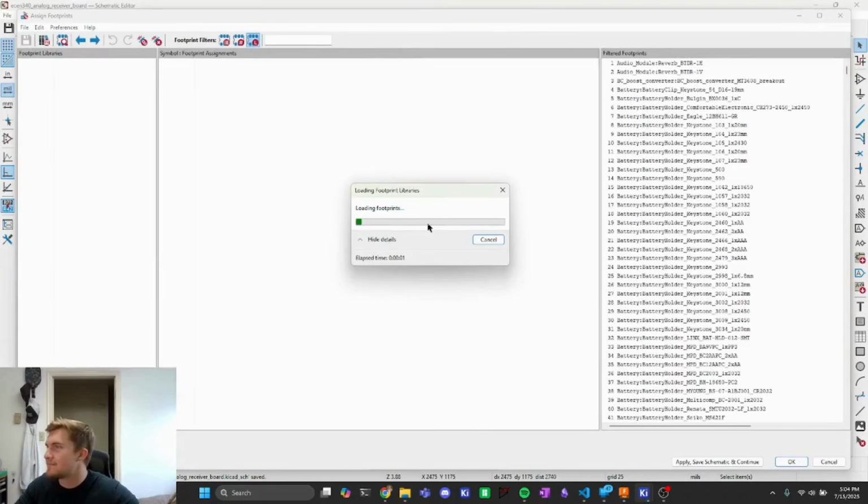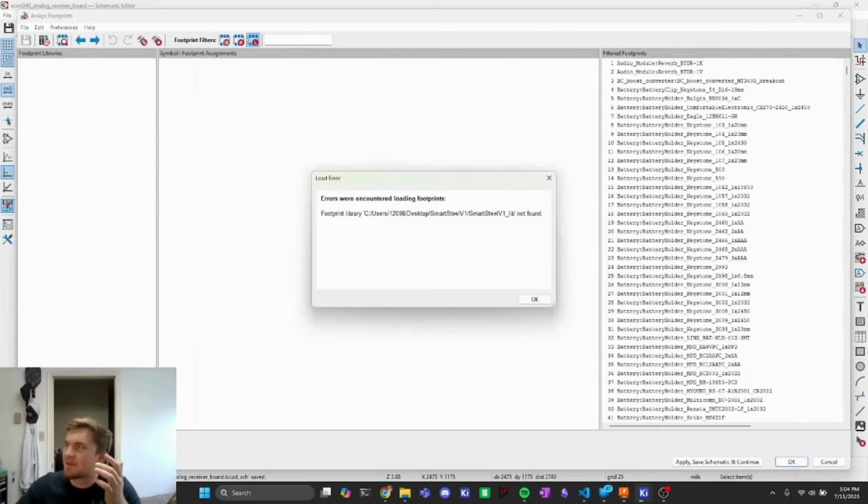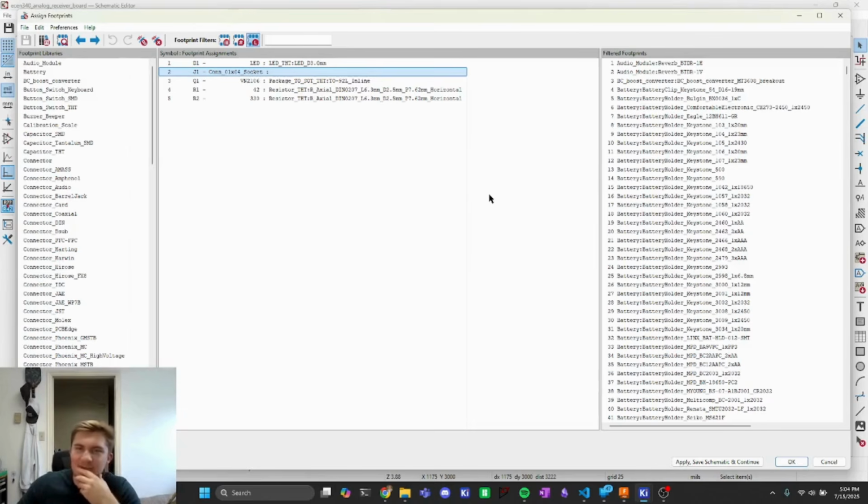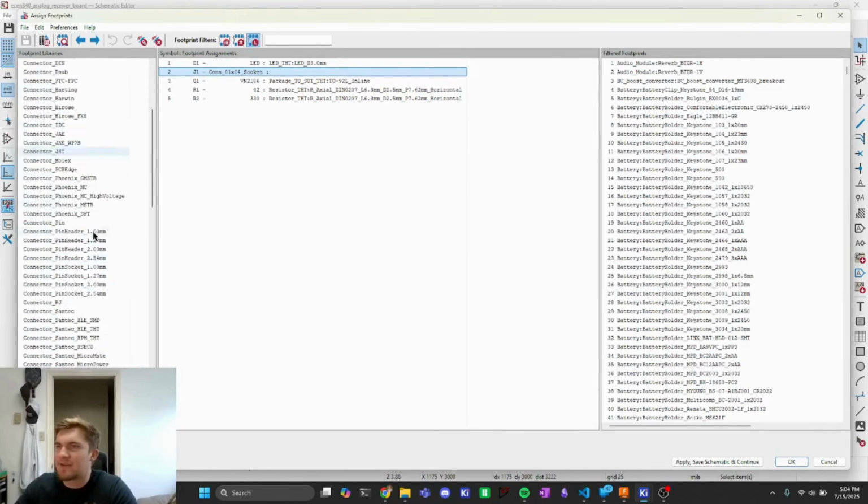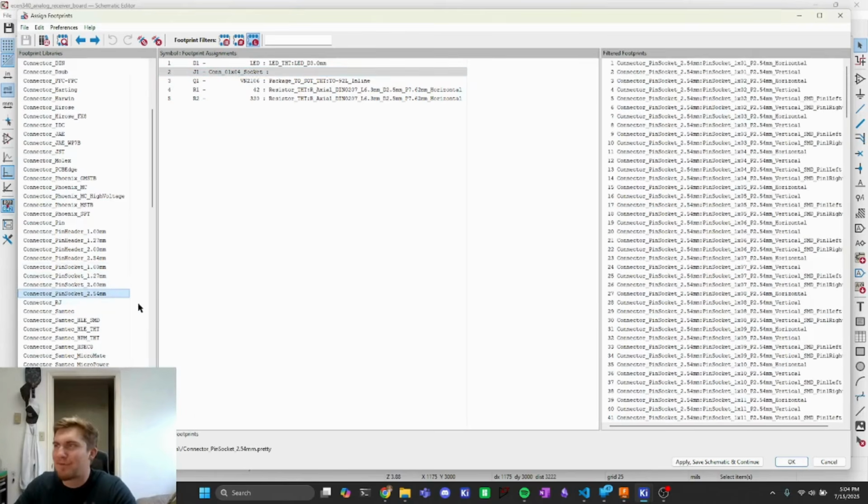Assign footprints. This is going to be a DuPont connector. DuPonts are great. They have this springy little fork on the inside of them that grab your standard circuit board pins. It is reversible, so you need to be careful with DuPont connectors, but they're still pretty handy. The most common size is 100 mils, which is 1/10 of an inch. So thank you, America, for using American units. It is 2.54 millimeters in metric. I might prefer one system of measurement.